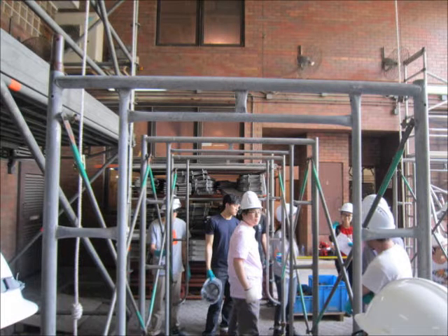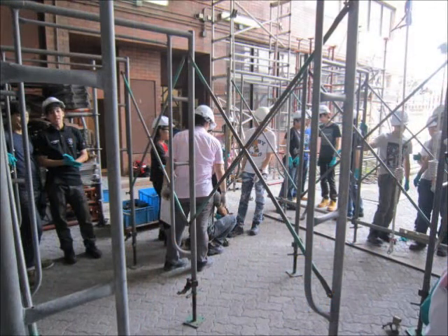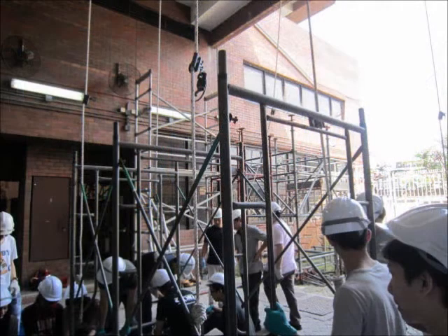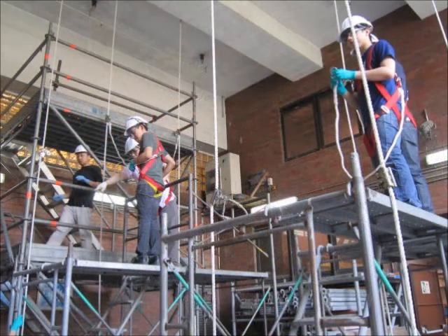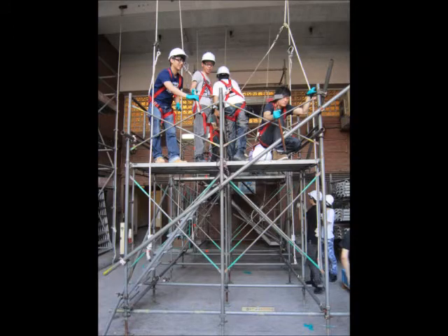Use double couplers and swivel couplers to fix scaffold pipes as standard ledger and bracing. Second, we fix the ladder and platform. Finally, we can use straight drawn pipes to fix the walk-through frame and adjustable head jacks.